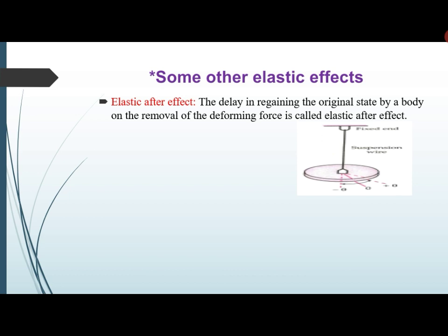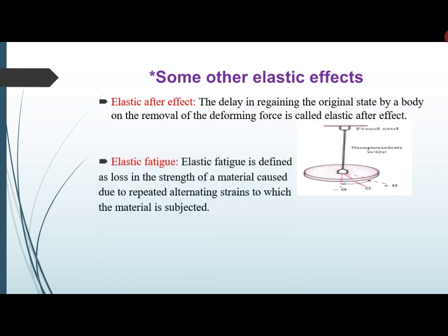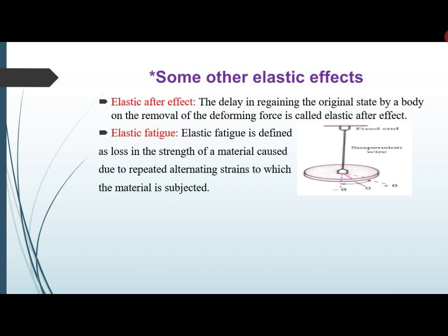Now we'll discuss these oscillations in elastic fatigue. As the name suggests, fatigue means tired. Elastic fatigue is defined as the loss in strength of a material caused by repeated alternating strain in the material. During these vibrations of the torsion pendulum, the wire is subjected to repeated alternating strains.